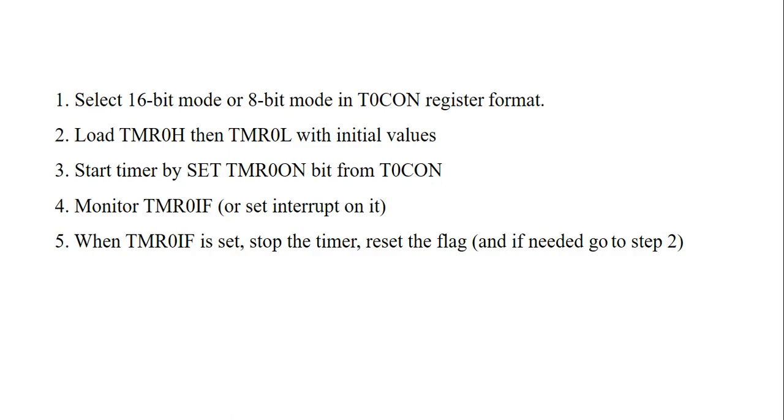Already I said that these SFRs are bit addressable, so a single bit we can set or clear. If you want to start or enable the timer, we can set that particular Timer 0 ON bit. Then monitor TMR0IF, which is from the INTCON register. This bit is used to tell whether the timer has overflowed or not. When TMR0IF is set, the timer says an overflow has occurred and the count is completed. Then stop the timer, reset the flags, and again load the count into TMR0H and TMR0L.